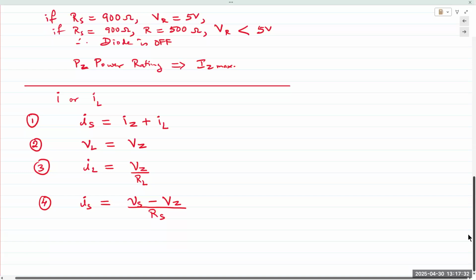So the question being asked is, could this be used more for voltage reference than an actual power supply? I would say yes and no, depends on your application. If it's a standard application, like let's say phone chargers, then Zener diodes are not the best. There are off-the-shelf voltage regulators available. They're integrated circuits, so you can just buy them off the shelf, and they have a few more components built into them. So the answer to your question is yes and no. Depends on the application.